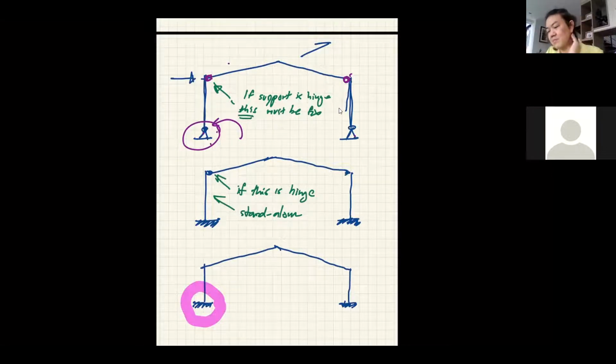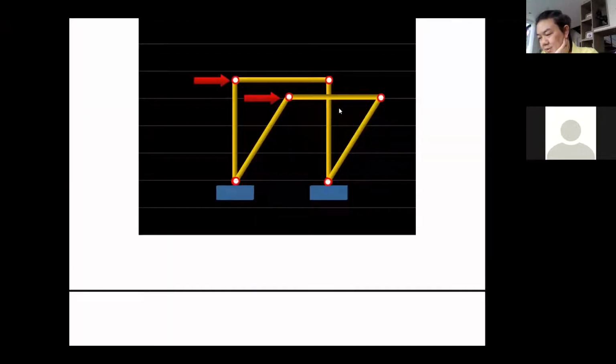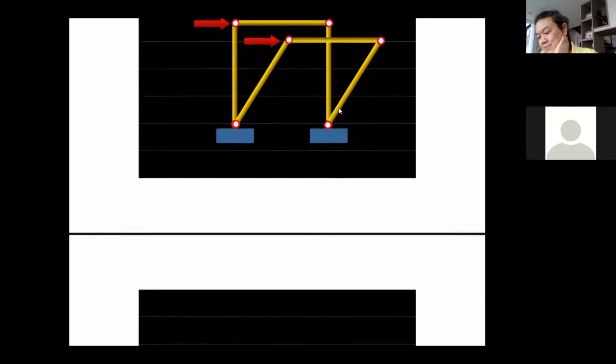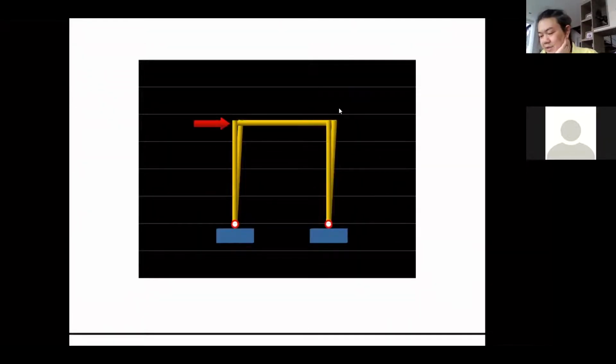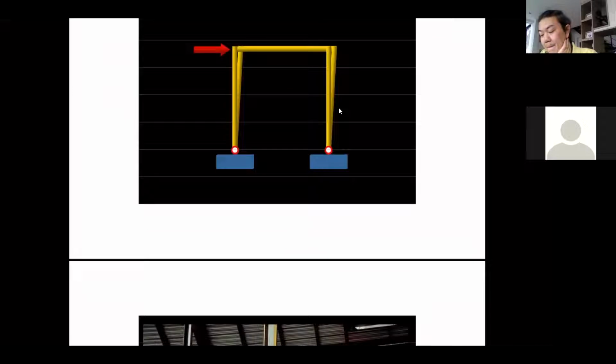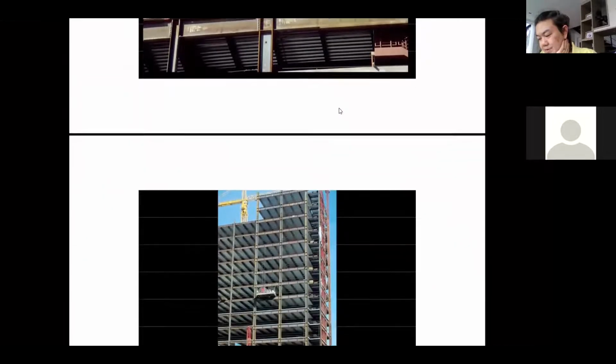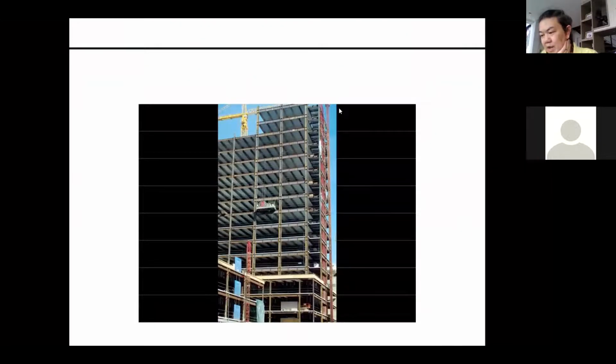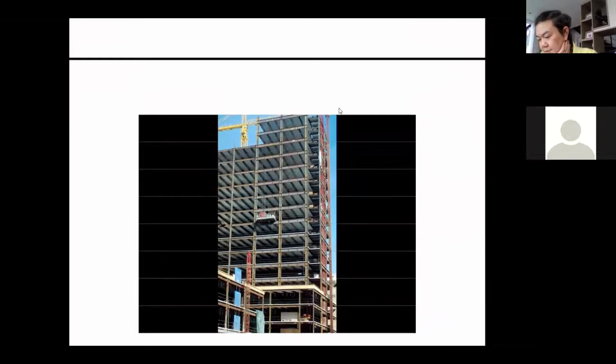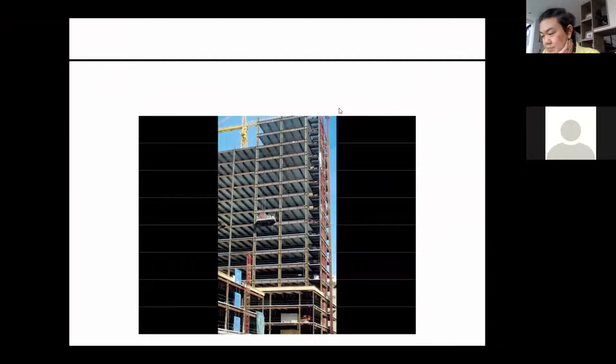All right, so we can come back here. So that's the whole idea of this picture. All right, so see the next picture. If it's fixed up top, now our system becomes stable. And this is the example of the framing system when we cannot have the brace, like that. See, no brace, and you have the full use of the area everywhere. But look at the details of the joint. That looks very, very stiff, right? Because yes, that's a fixed support.